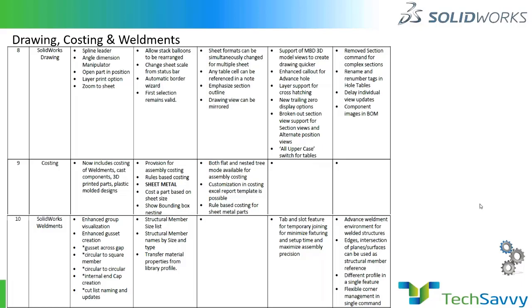If I tell you in a very small summary, costing is a tool which will help you to estimate the cost of your part, including each and everything. So if your part is made from sheet metal, we start from a blank plate to laser cutting or tool-based cutting, and then go for bending, then we move towards forming and other areas. So all these things were there. All these types of small costs you can put inside our costing tool.